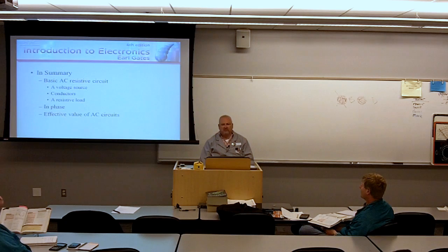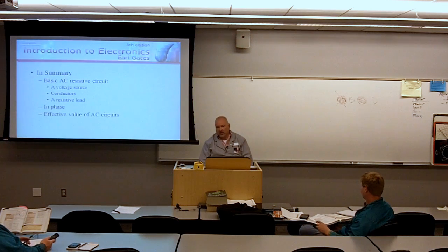If I give you a peak value, say, why the heck is Joe giving me a peak value? Convert it to RMS. If I give you a peak-to-peak value, convert it. If you look in a radar tech manual, you're working on a radar and it gives you a peak value for something, assume they want you to know the peak value. Some stuff is important, that you achieve a certain peak voltage. That will be specified in the manual. If the manual just says 14.2 volts AC, what do you assume? RMS. So if it's not labeled peak or peak-to-peak or anything else, assume RMS.